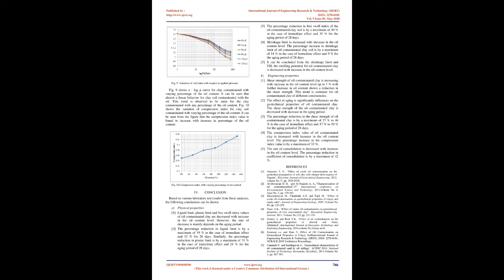It is shown from the figure that the shear strength decreases with increase in the oil content. The immediate response and the response at the end of 7 and 14 days show a very small increase in the shear strength, but there is a considerable increase in the shear strength in the case of the soft clay samples tested after 28 days.